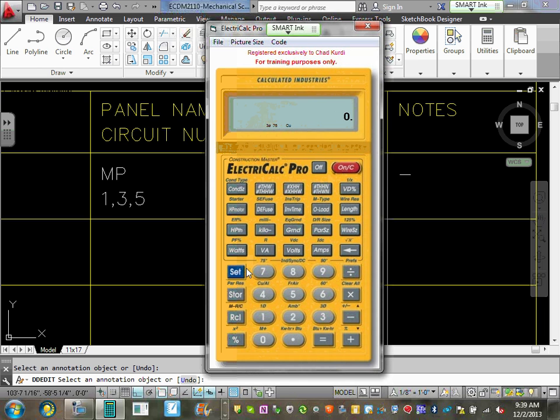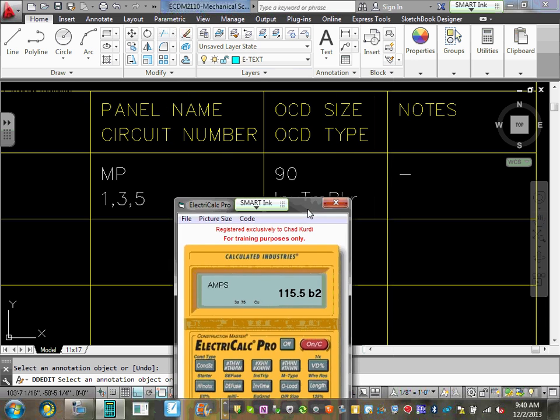Or you can use the calculator. Clear this. You're going to, I believe, set an inverse type. Oops, wow. No. Here you go. Here's my amps. Set an inverse type. No, I think I screwed up here. So let me put one more, 15 horsepower. Amp is 46.2, okay. And I need inverse type here. 115.5. The same calculation that I came up with. So my overcurrent protection device is going to be 125.